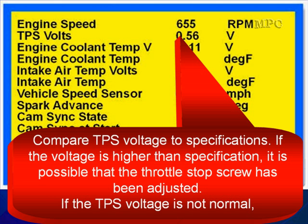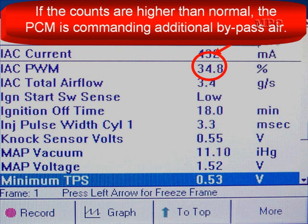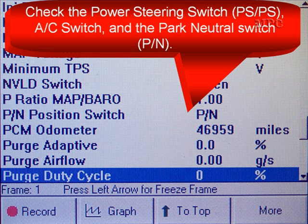If the voltage is higher than specifications, it is possible that the throttle stop screw has been adjusted to compensate for a problem by a technician. If the TPS voltage is not normal, look at the IAC counts. This is a normal reading, this 34.8, on a vehicle that's in closed loop. If the counts are higher than normal, the PCM is commanding additional bypass air.